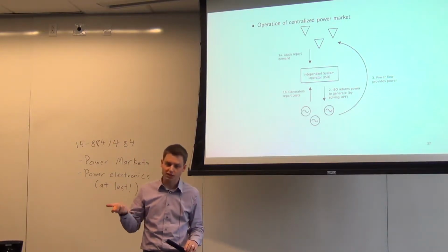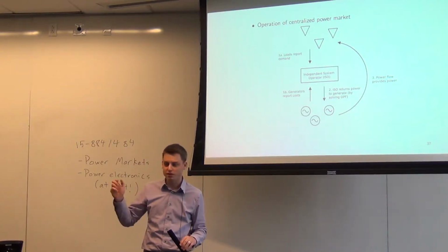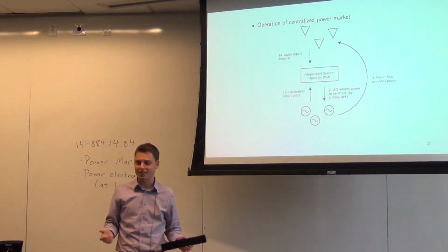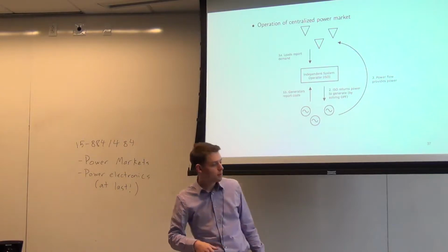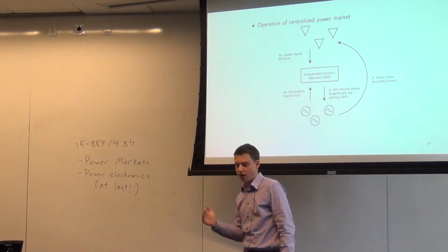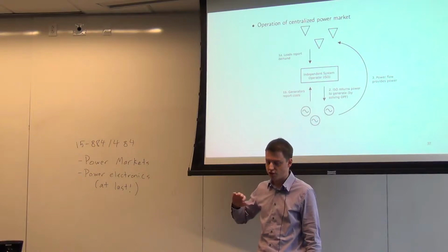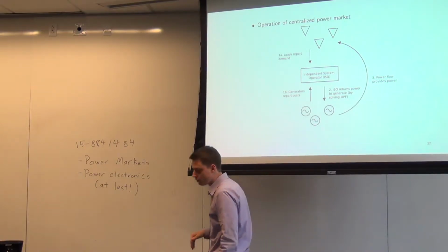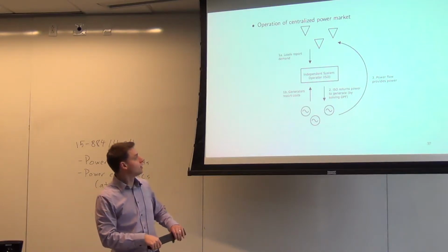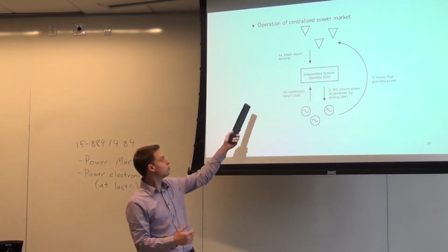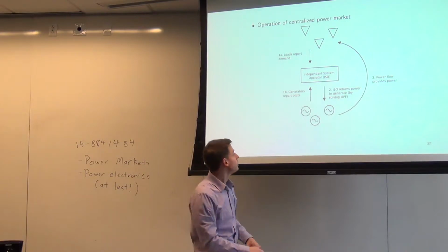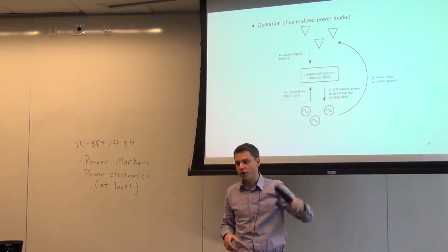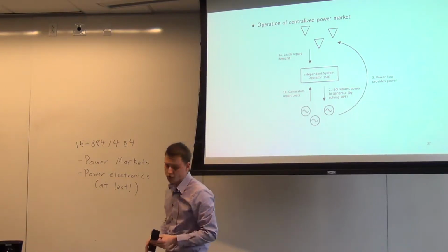It's going to be almost impossible to ever get perfectly right, because I could choose, in some sense, to turn on a light or not, and that will change the demand a little bit. So the little bits in the margins are actually made up using a different system than this. This is really the market for the big allocations of power that you want to do at the grid level. The way that works is that the loads all report how much they're going to need. Again, it can be approximate, but they report it to this central operator called an ISO or an RTO or something like this.